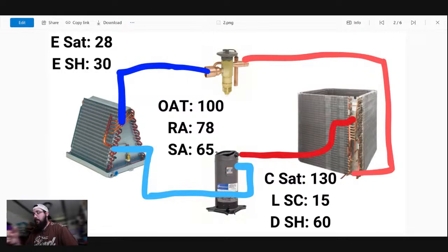So we see low charge. Okay, so we're talking through the low charge now and non-condensables. Non-condensables is an interesting one. I didn't think of that one. Okay, so plenty of subcooling. All right, so now we're getting into TXV shutting down some. Touch really quick on discharge superheat.